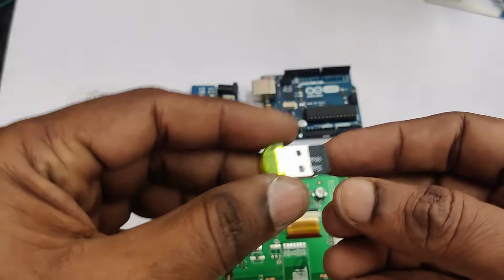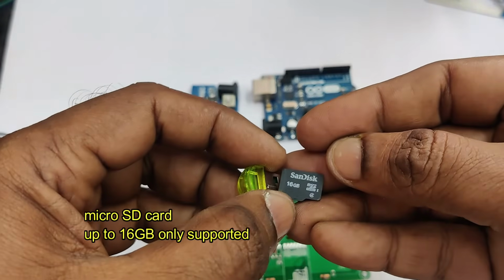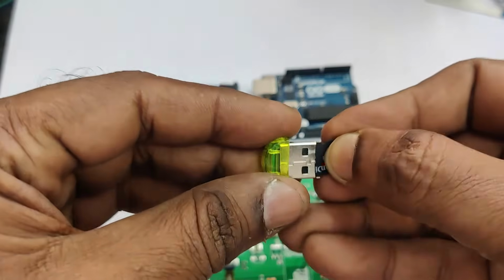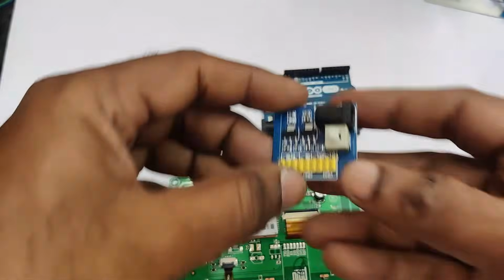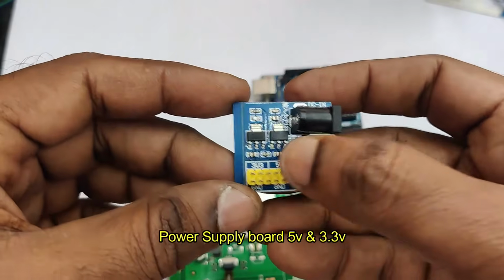We require a micro SD card like this. Maximum up to 16 GB only is supported by the DWIN display. More than that is not supported. We need a card reader also. And an external power supply is required to supply 5 volt to the DWIN display.